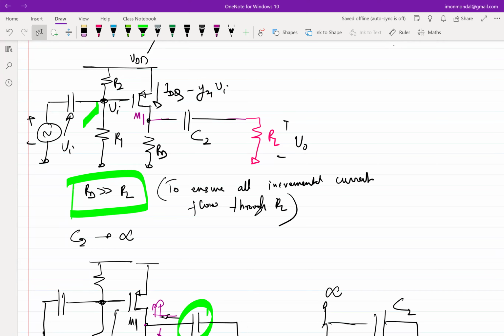If you keep on increasing RD, or in that case RL, what's going to happen? It's going to get into the linear region. But if I have to fix it, what should I do? Increase VDD. If I increase VDD and keep the voltage drop across R2 the same, which means I'm keeping VSG the same, then I have a provision of lifting the gate voltage. I can lift the gate voltage sufficiently to get the transistor back in saturation.